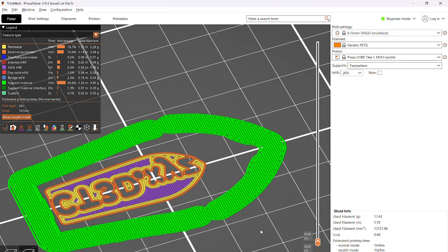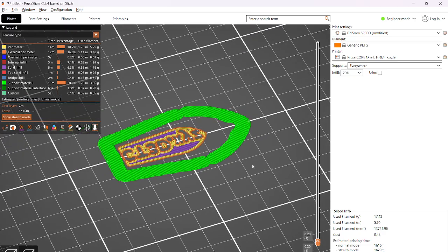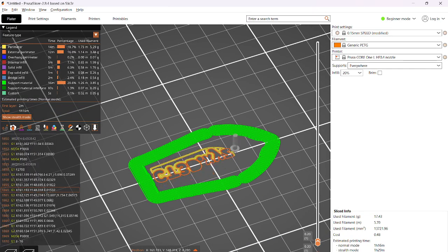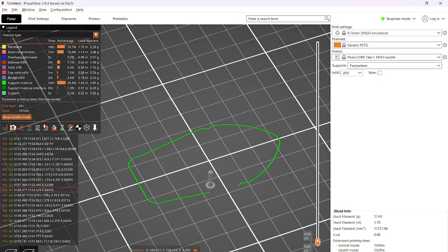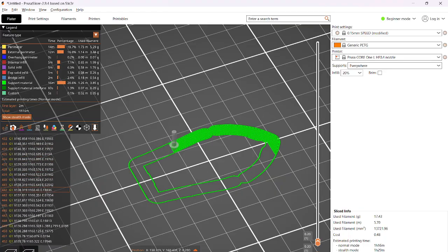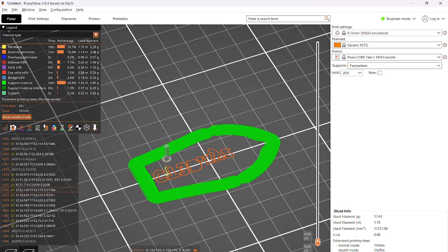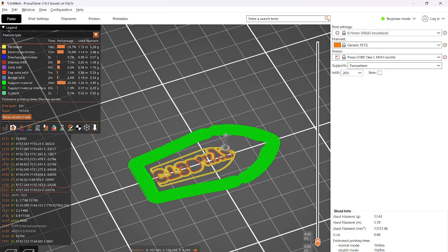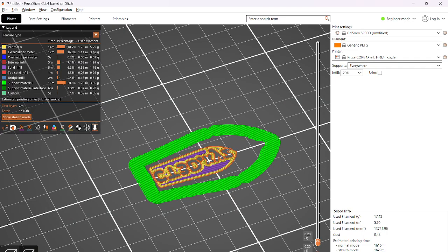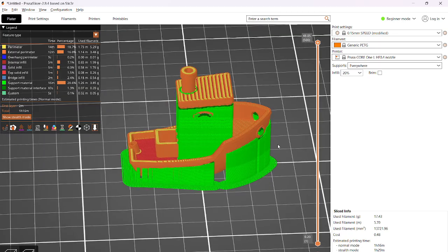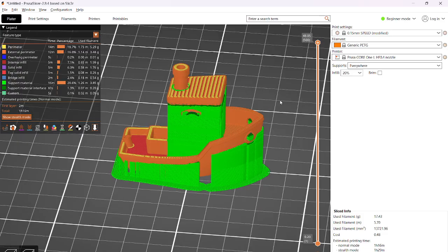But yeah, you can go up and visualize it. If you mess with the horizontal slider, you can go layer by layer and see the exact path that the printer is programmed to move on. You can see that arrow represents the nozzle, and if you go across, you can see the path it takes. It draws these lines, just the supports. This orange stuff and yellow stuff is the bottom layer, and then it'll fill it in with that purple. But it'll do that over and over again, in this case, 500 times to make your part. So, yeah.